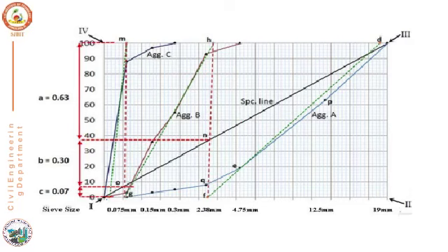After it is ready, what we have to do is plot the sieve size. Look, it is plotted here. We will see that 100% and 97% corresponding to that will have 19 mm sieve size. If you see here 78%, go up to meet this point and drop it down, it will be for the 12.5 mm. Similarly, plot the sieve sizes, and once the sieve sizes are ready, in the next step